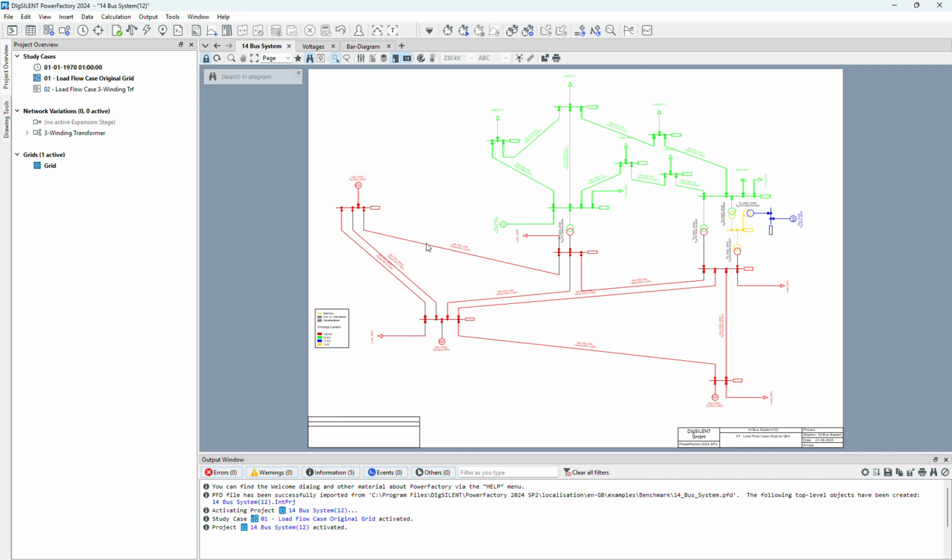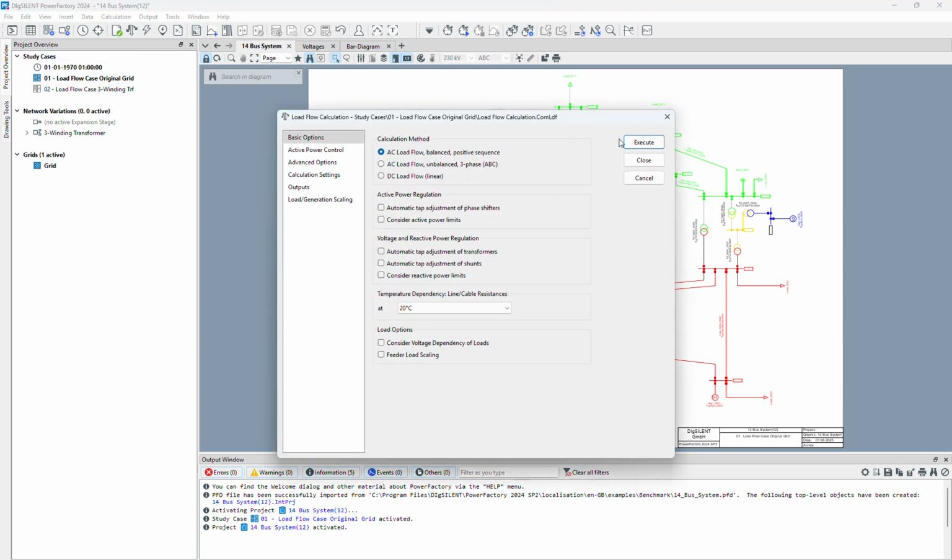So for example, we want to install overcurrent relay in this line, in this side. So for doing that, first we should design the overcurrent relay that we need. For designing the overcurrent relay, we need first to see how much is the pickup current. Normally the pickup current for overcurrent relays is 25% higher than the maximum rated current. And we need the TMS, and the TMS for the first overcurrent is normally 50 milliseconds or 0.05. So first we should make a load flow.